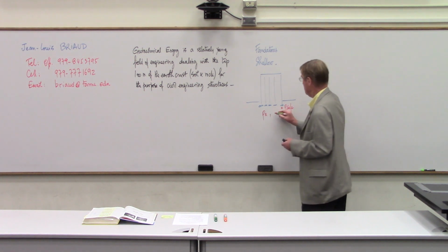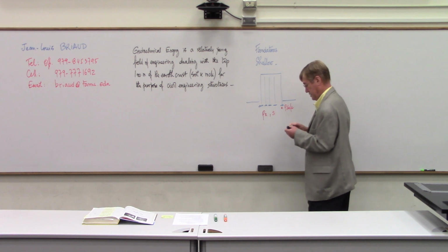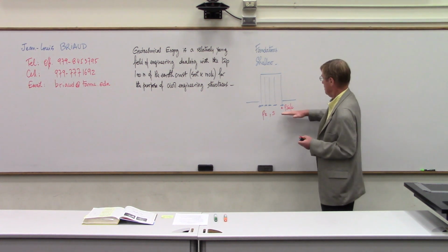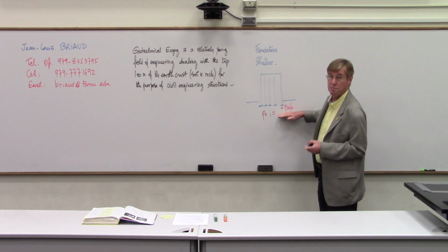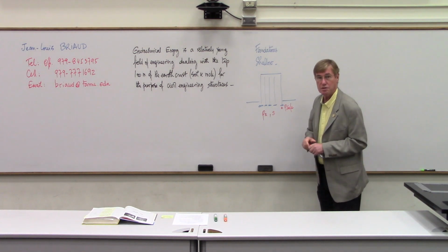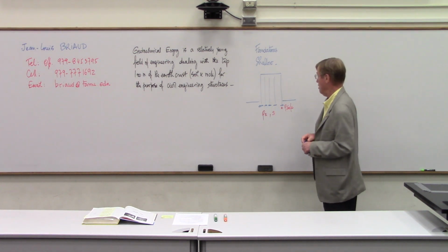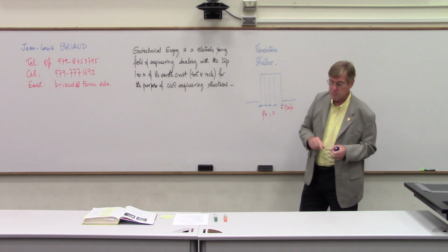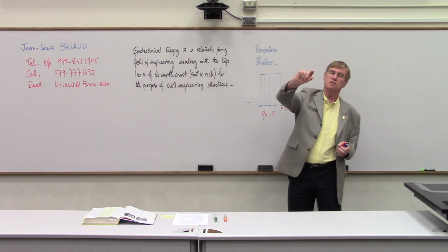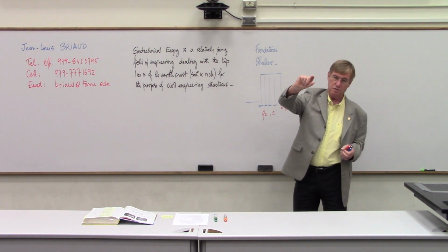But the second question is the settlement, S. In other words, even though you have a safe pressure, how much is this building going to settle? And there we say, well, we'd like this building to settle only this much, 20, 30 millimeters.